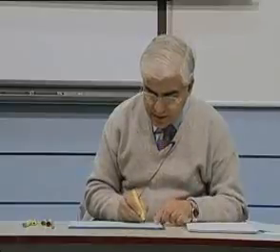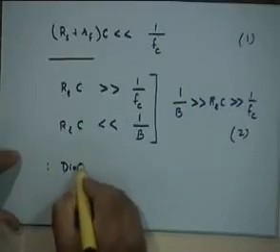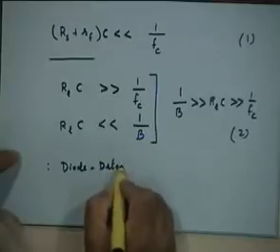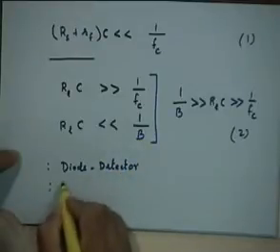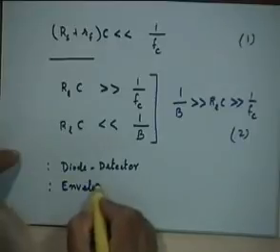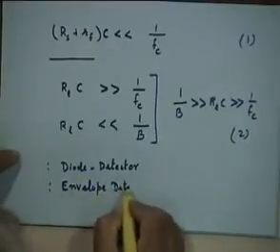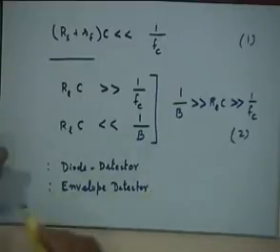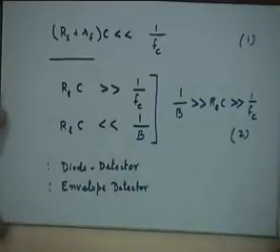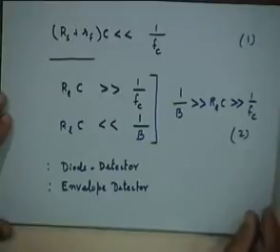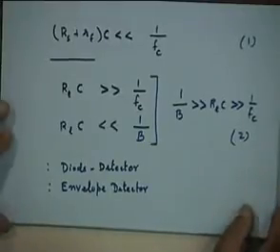Okay. So that is what the envelope detector is all about. This is what we call the diode detector. It has various names. We also call it the envelope detector. As you can see, just with these three components, a diode, a resistance of a sufficiently large value, and a capacitance, we can build a very simple demodulator, right? And that's what most of your AM receivers do, that you use in your homes or whatever.